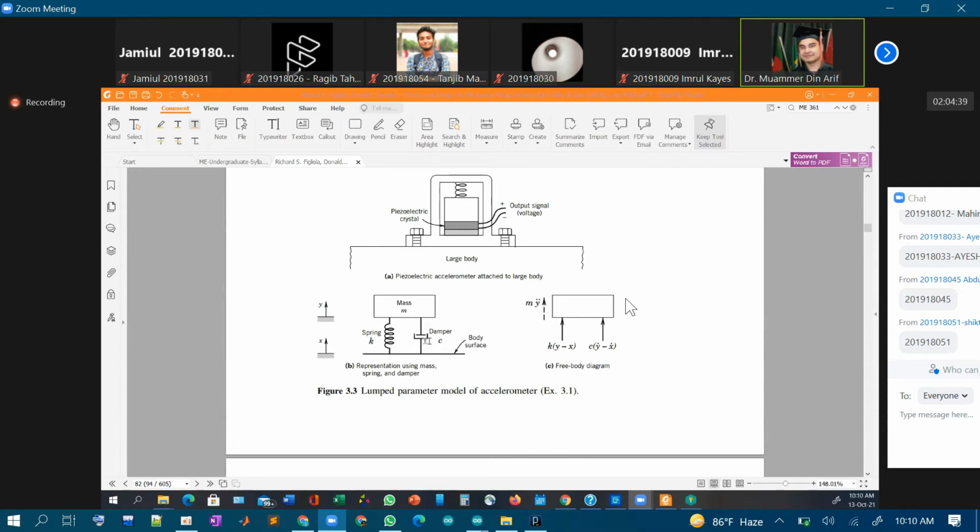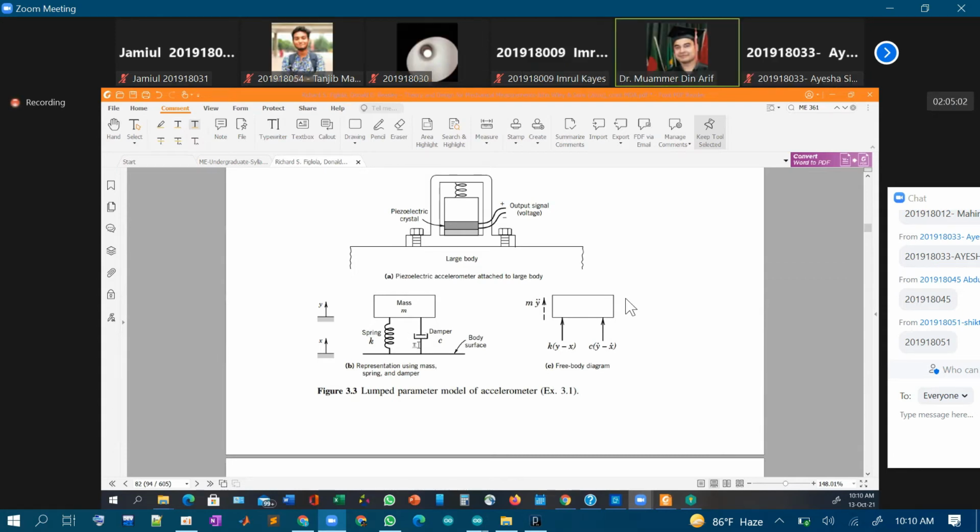Essentially, that is what the damper is. Basically, when the piston moves, it squeezes the air, but a liquid cannot be squeezed, so it slowly goes through the hole. There are some holes in the piston, through which it flows and slows down the piston. That's why for higher force applications we can also use oil damping instead of air damping. So that's basically the idea.